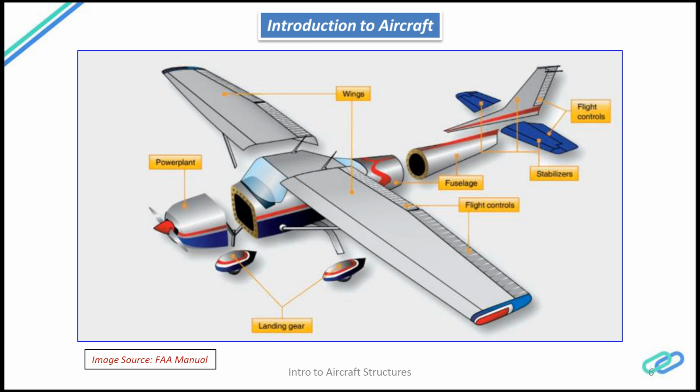Internally there will be a hydraulic or pneumatic system that will transfer the effect to these flight control surfaces. And for yawing, for the rudder, there will be a pedal, something similar to the brake pedal in your car. In this way you will deploy the yawing motion, deploying the rudder using the pedals.